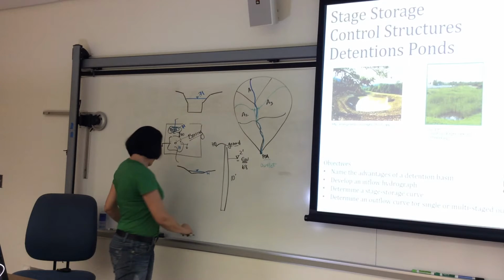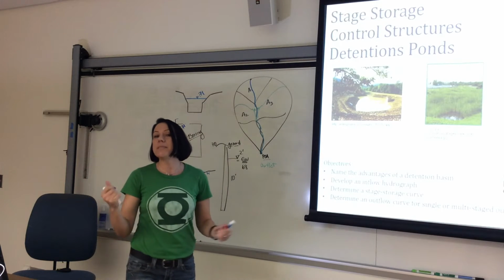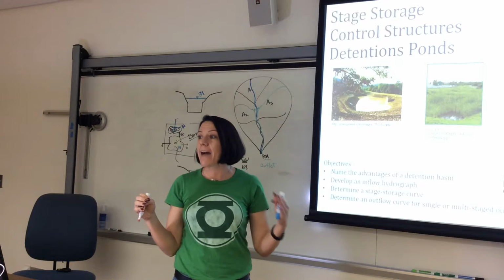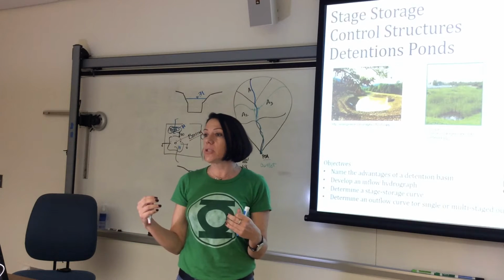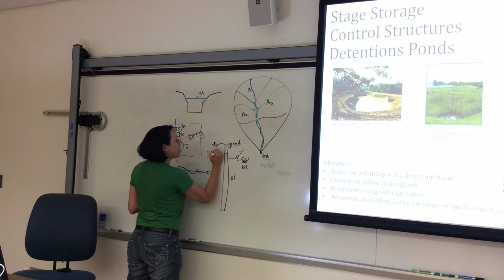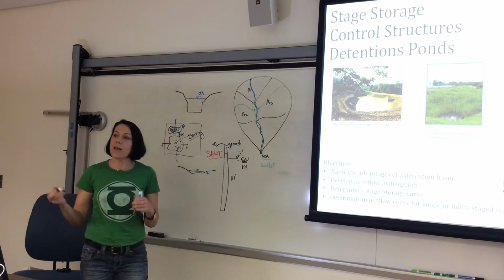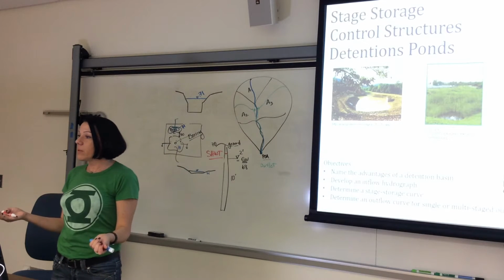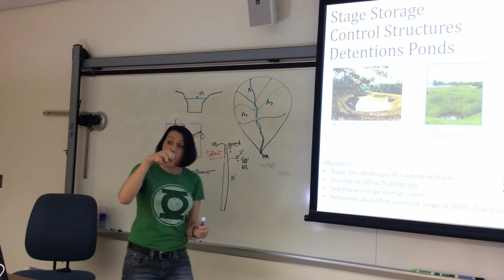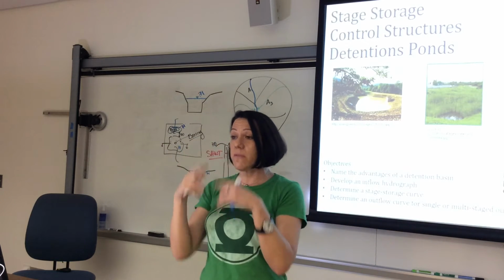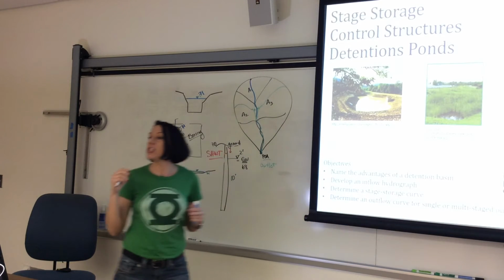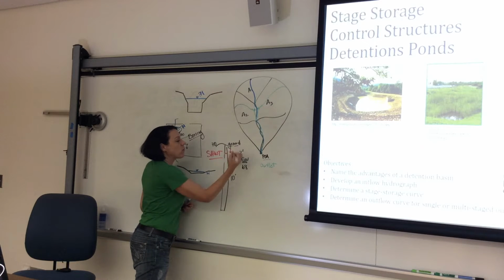But here's the thing. There's a thing called the seasonal high water table. And I'm telling you a lot of things that aren't technically in textbooks, but these are the types of things you have to know when you start working in the industry and permitting with these agencies. Seasonal high water table means we know we get our summer rains, right? The summer rains come up, and when they pull these samples, they can actually see in the columns of the soils how water may fluctuate. There's some type of indication that normally it's only 1 foot.